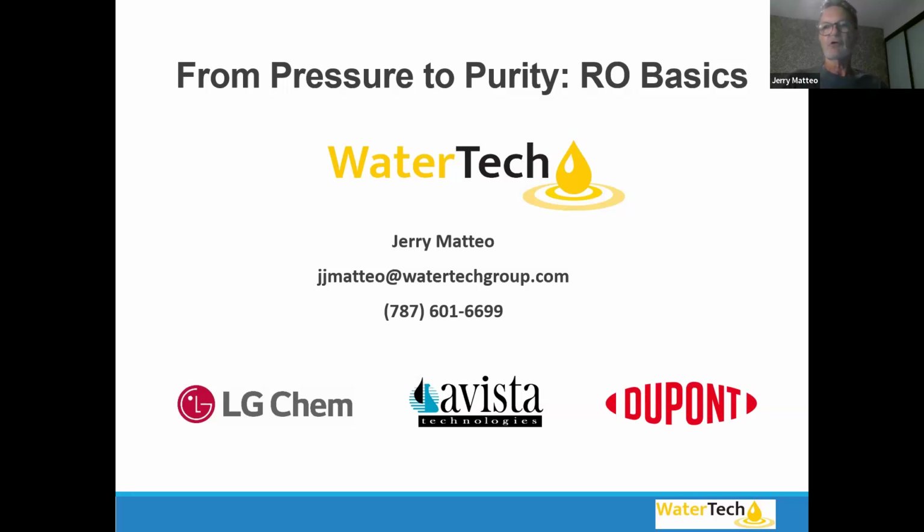So there are anti-scalants that help keep it in solution, but I think you might be referring to green sand and all those things. If it's high enough, you probably need that kind of a thing. A green sand, or there's something out there, Philox, that's this manganese dioxide, real high concentration manganese dioxide. And I think how that works is both of them oxidize the ferrous iron to ferric and then they filter it out. So depending on how much iron there is in there, iron can be a killer on membranes. It can be, but it depends on the amount. So it all depends on that. That water analysis is like the beginning of everything for us, where we see what's in there and then we start to battle it from there.